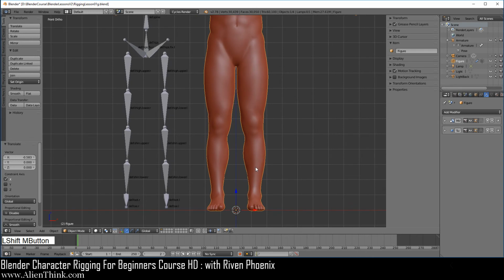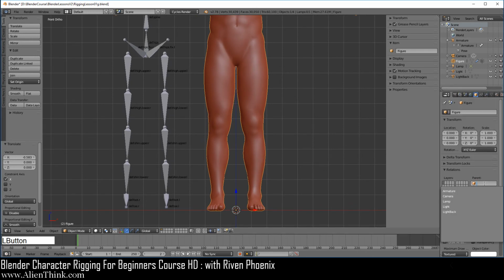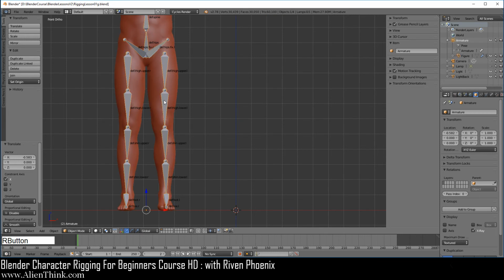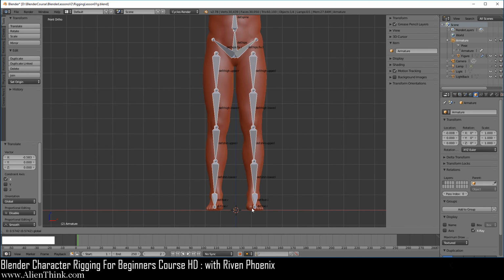Now click over here, and now when we go to the object tab and click on armature, now you understand what's happening. This is the same thing. So now if we click on the armature, which is the parent, and move its origin point to the center of the 3D grid, you can see why the figure was moving when we had done it this way.